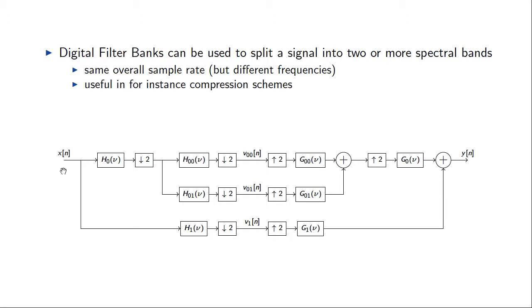So you begin with taking your original signal that you want to compress and store, and you split it into several different frequency bands, or signals containing the information in several different frequency bands of the original signal. And then you individually compress and quantize these in order to store them efficiently. And then you can base the different quantization on how subjectively sensitive you are to quantization effects in each of the individual frequency bands of the original audio spectrum, and that will lead to very efficient compression schemes, like for instance MP3 or AAC.